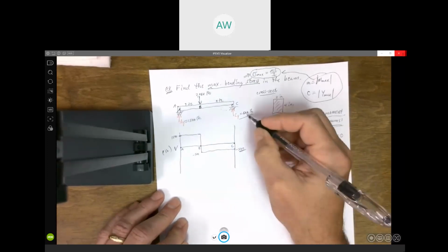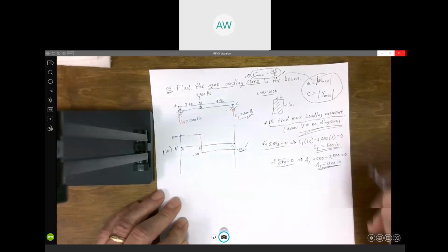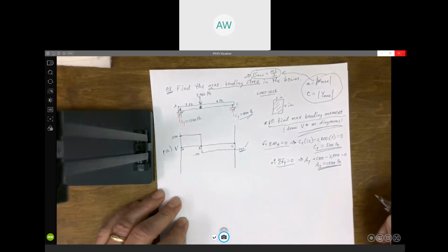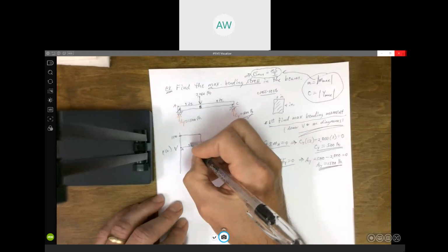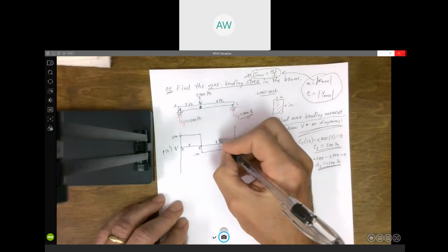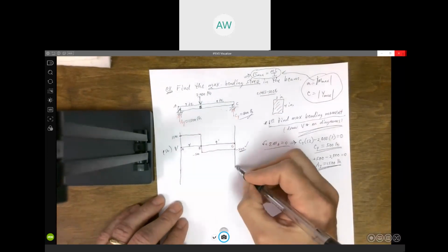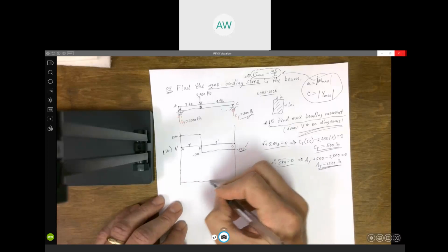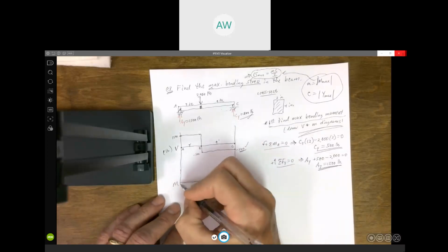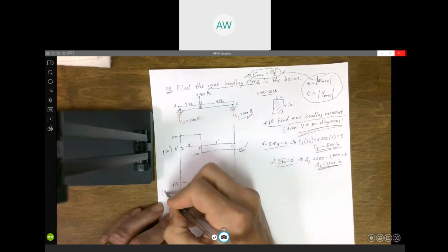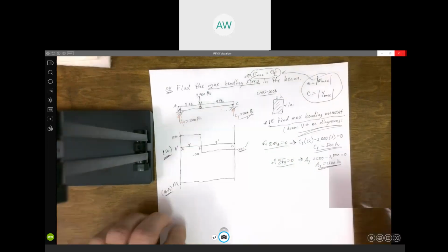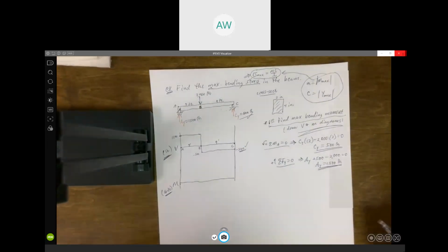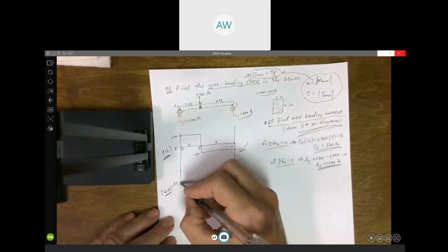And notice that does check with CY. And now we know this is 3 feet. This is 9 feet. And we need those dimensions because, remember, to get the moment, these would be in foot-pounds. So don't forget, put units on your shear moment diagram.